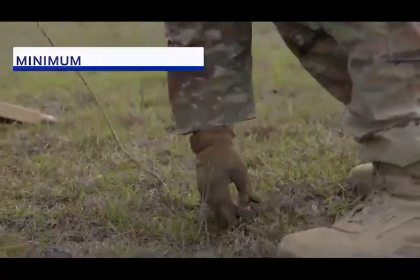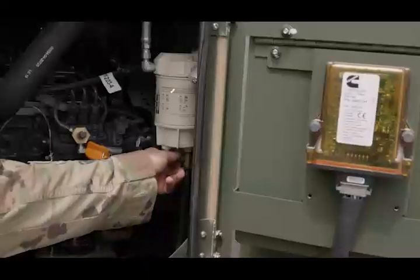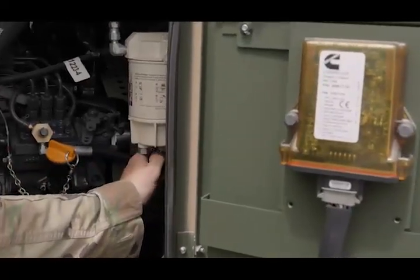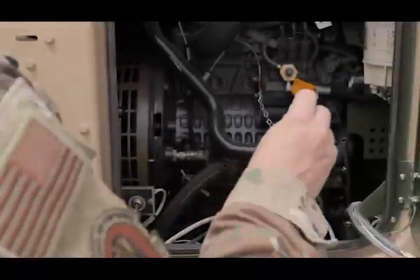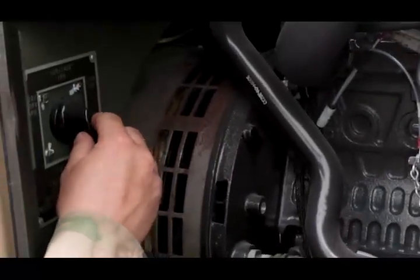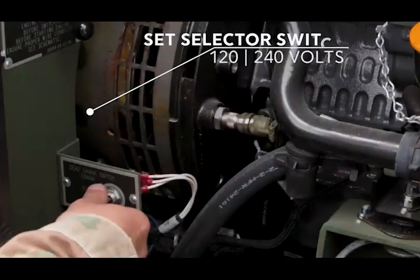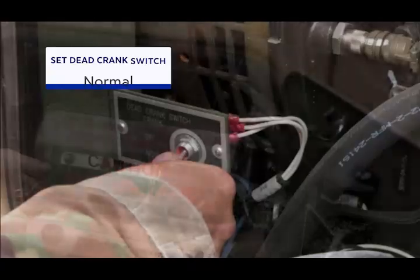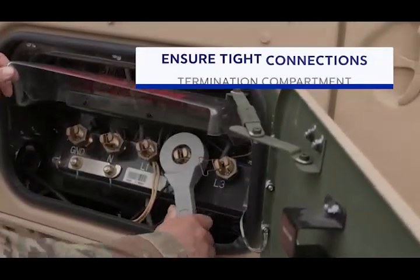Before starting the generator, check the coolant level, turn on the battery switch, check the fuel filter and water separator. Drain water if present. Check oil levels. Set the selector switch to 120 or 240 volts. Place the dead crank switch to normal and ensure all connections are tight in the termination compartment.